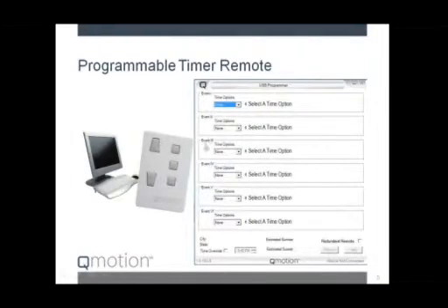On the bottom of the window, you'll see the time on your computer. This time will reload into your remotes. So if it's not the correct time for the remotes, set the time override checkbox down there on the bottom. When you plug in a transmitter, the buttons for retrieve and apply will become active, as you'll see on one of the next slides. And instead of saying device not connected, it will change the terminology there.